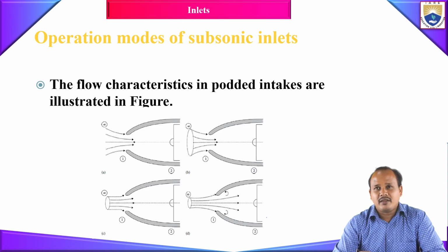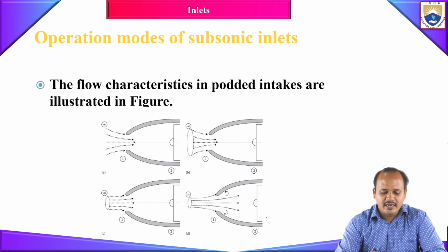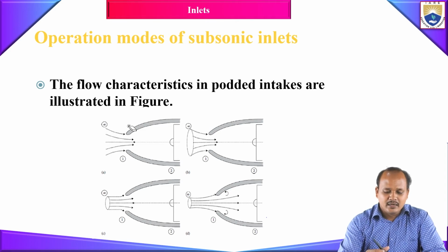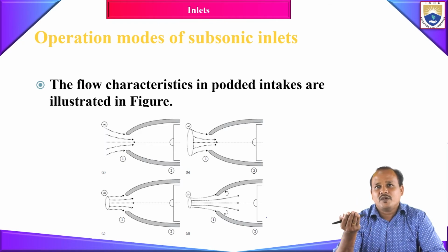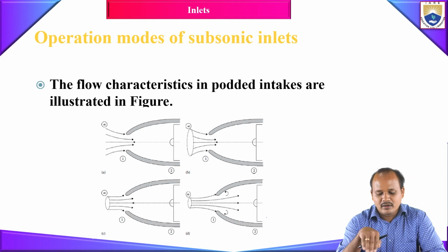If the engine is still, how does the air enter? Because we rotate the compressor. When your compressor is rotating, it is going to suck the air from outside. Since the air is still, the air from throughout the surrounding atmosphere will move towards your compressor.